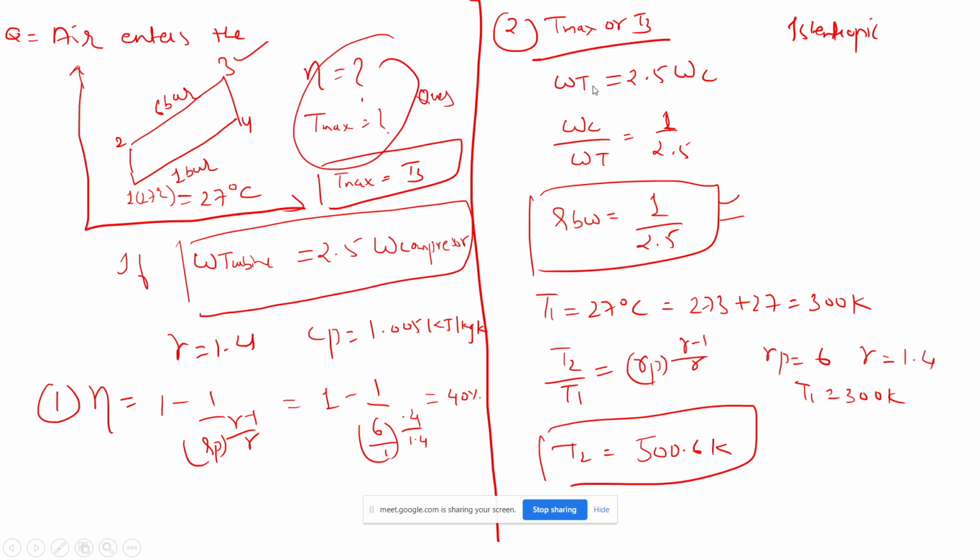Here we can get compressor work upon turbine work, which is the back work ratio. So from here we can also solve by putting that formula. But you can directly put the values here also, turbine work and compressor work, and from here you can get the values. There are two methods I said: either put the values directly in the turbine and compressor work,